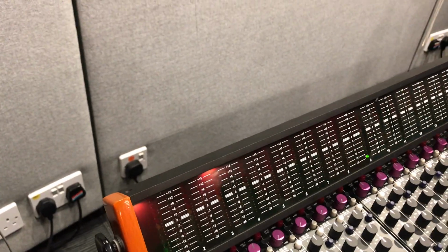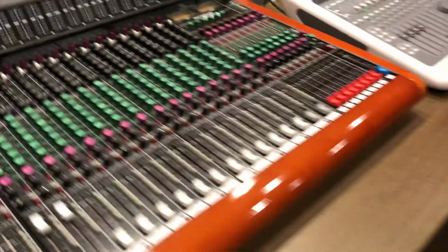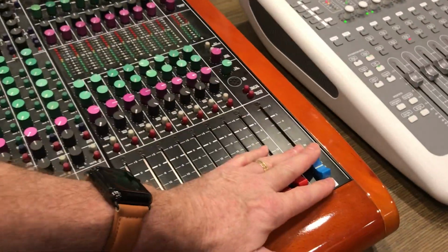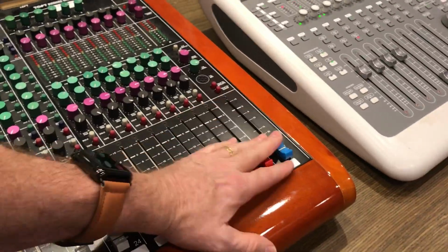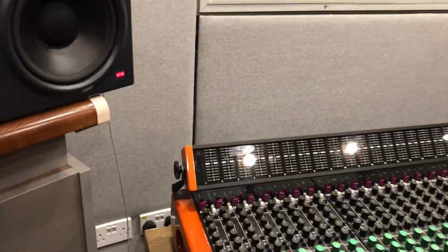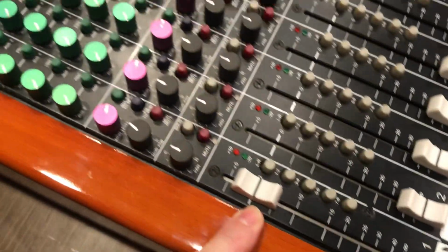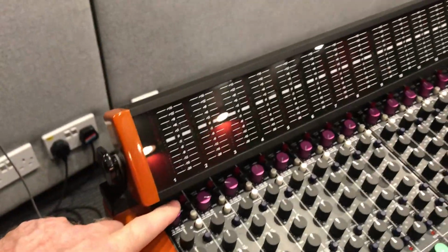That can damage the speakers. So if you're unsure, what's best practice, including myself, just bring those all the way down. Connect your microphones. Ensure phantom power is on. Raise this fader up to 0, adjust the gain input.